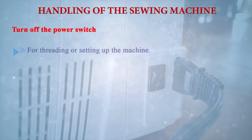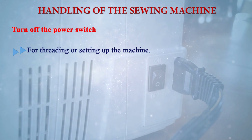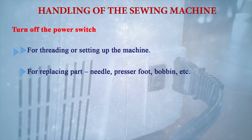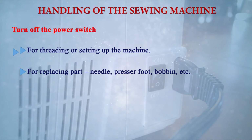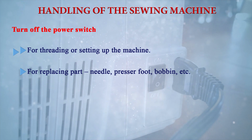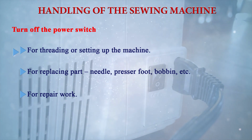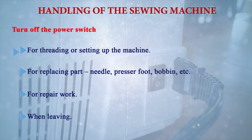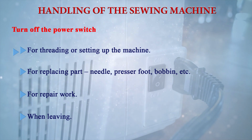So you have to turn off the power switch. Turn off the power for threading and setting up the machine, and for replacing parts like the needle, pressure foot, bobbin, etc. When you are doing the repair work, or some oiling of the machine, you have to turn off the power. And when you have completed your work and done your stitching, then just turn off the power of the machine.